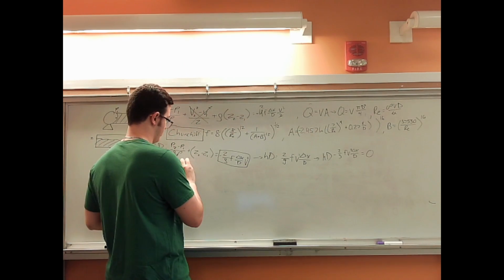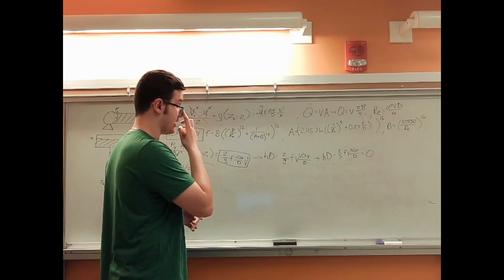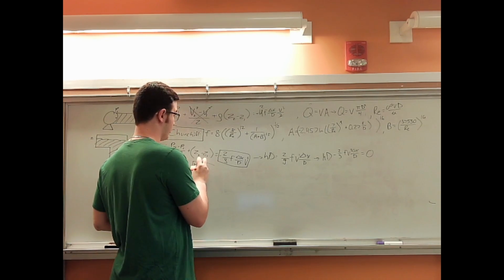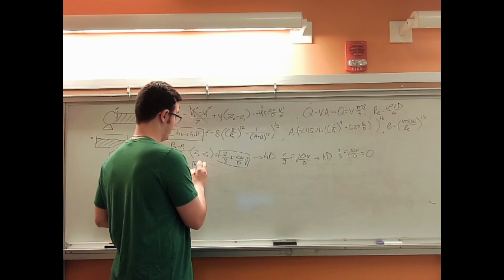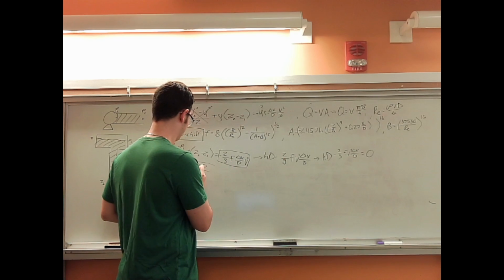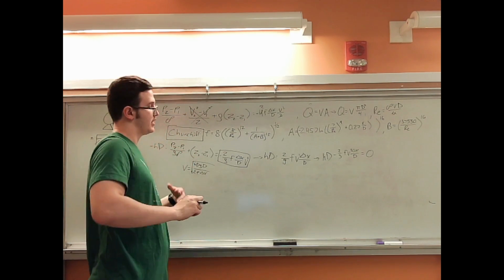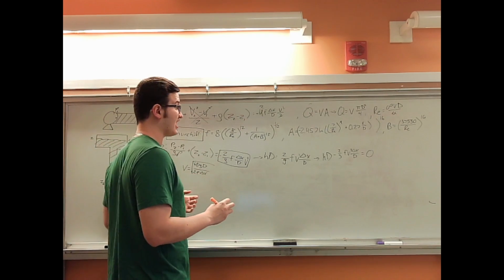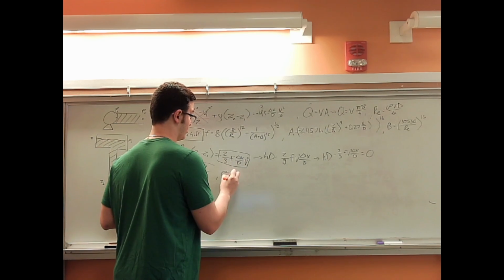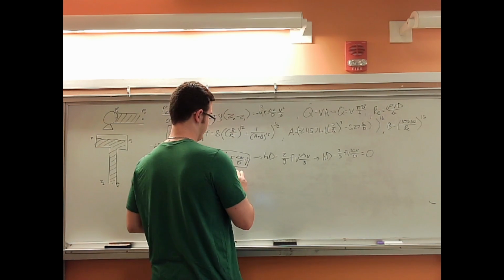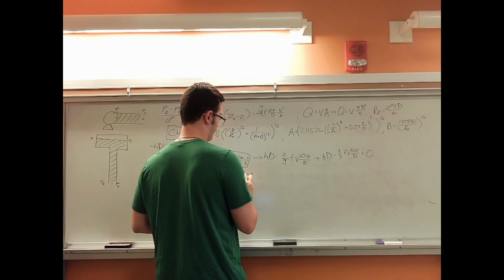So by moving everything over, v, the velocity, is equal to the square root of the head drop multiplied by the gravitational constant g multiplied by the diameter of the pipe divided by 2 divided by the friction factor divided by the change of position. That will just be the length, but that's not very important here. And we also know that Q is equal to V multiplied by pi times the diameter squared over 4.